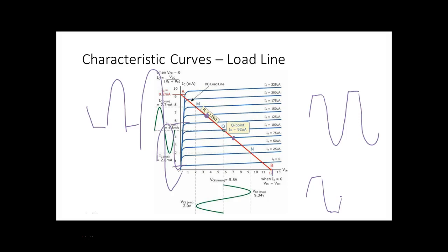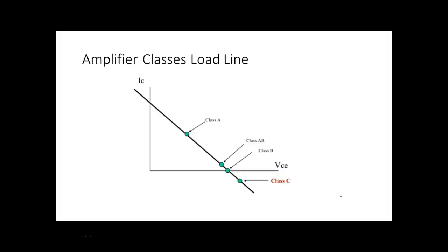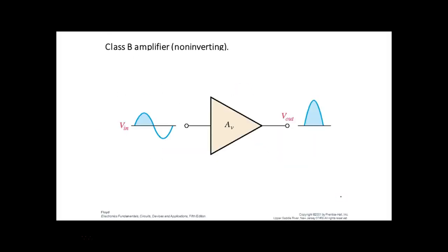Oscilloscope. Usually to troubleshoot these audio amplifiers, you almost have to have an oscilloscope. So this would be a Class B. We could have a negative Class B or a positive Class B, right? A positive pulse would be using an NPN transistor, and a negative pulse would be using a PNP transistor. And what we do on an AB is we just hook those together, and do something about the crossover distortion.